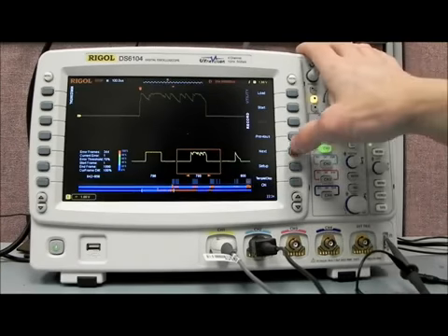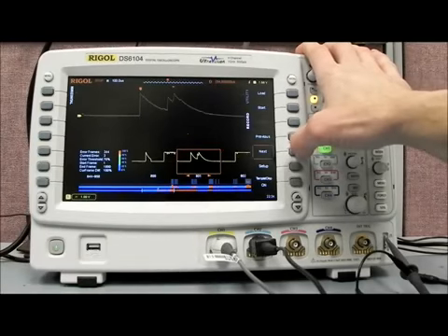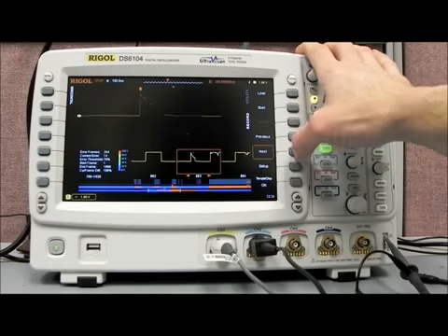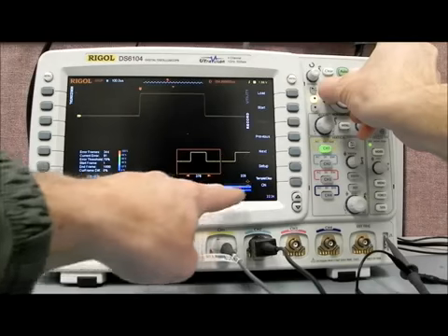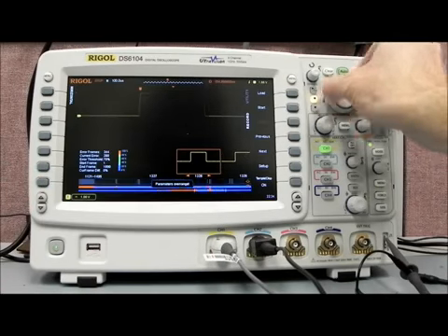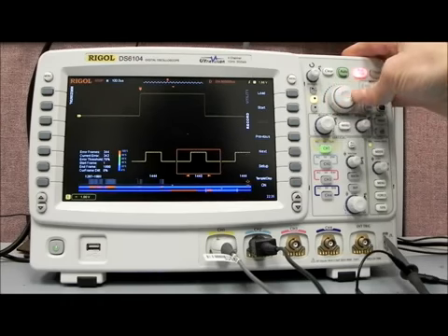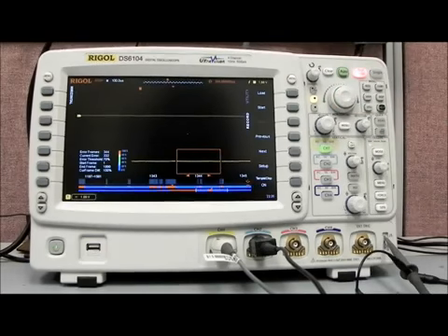You can very easily go using previous or next. You can go to each of the failed waveforms, and cycle through each and every failed waveform. Or again, you can use the fast forward key, and we're sliding along very quickly through that entire waveform. Or you can go one frame at a time by using the inner knob like that. Very fast and easy way to analyze a standard waveform in order to collect data over a particular period of